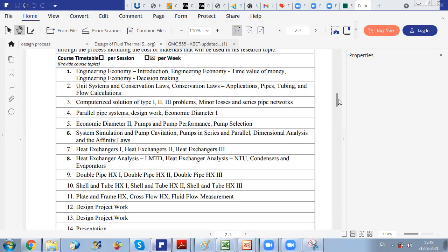You should understand your problem. You should know your boundary conditions. What I mean by boundary conditions is the inputs that you should impose on your system. So let's say you have a ventilation system. You should know the heat loads generated by occupants, by, let's say it's an office, by computers, by lighting, by the heat fluxes coming from outside. So it will depend on the envelope of your building, on its level of insulation, on the U values of the wall. All of these will be taken into account when you draw your geometry.